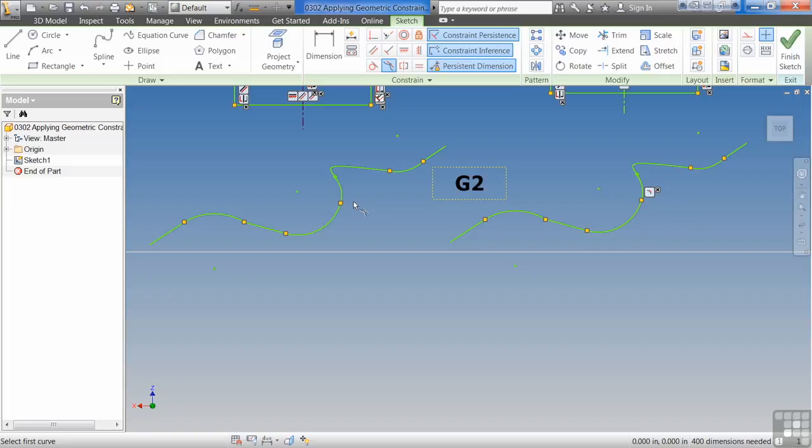If you look down at your mouse, I guarantee you there are lots and lots of angles and curves and grooves, and usually it's a beautiful shape. Even the cheapest $5 Dell mouse is still a beautiful shape if you really think about it. Somebody spent a lot of time making sure that you can't feel where the edge of that mouse is. Even though there's a radius on it, and you know that the top of the mouse is a lot flatter, almost horizontal compared to this edge of the mouse, you can't tell where one plane ends and the other begins, because it has a G2 constraint on it. It's perfectly smooth. And there's actually a mathematical formula that's involved in that, but just kind of a brief overview of the G2.